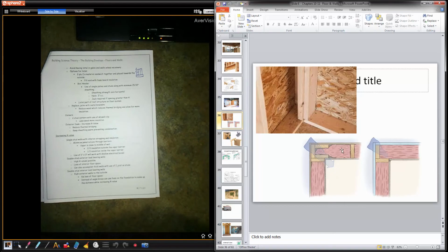Here, the typical corner we do is we don't have that stud. Some people put that stud in there for backing for exterior finishes. Not really required. And you can see what it does to the insulation. So some people think backing is more important than insulation. We could put a thinner piece of material there, but again, I've never put a piece of wood there, and I put on all the types of sidings.